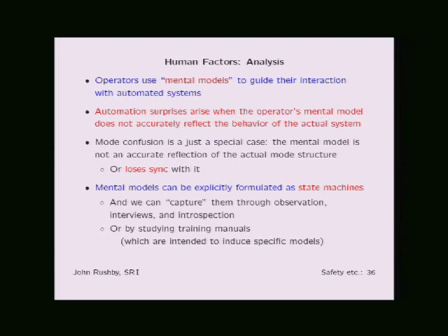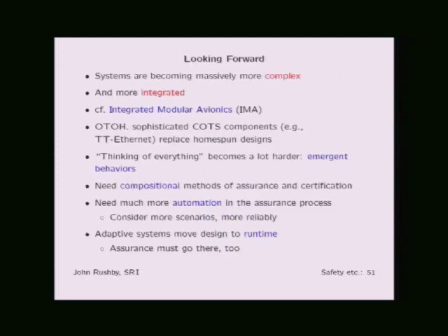All right. That's all I have for this lecture today. What we talked about was faults arising in sensors and in computers. We talked about how you can deal with faulty sensors using intervals, and deal with faulty computers using redundancy, n-modular redundancy, and voting. We talked about synchronized versus unsynchronized implementations. Then we talked about mode confusion, and how to make sure that the mental model of the human operator is in sync with what the system is actually doing.